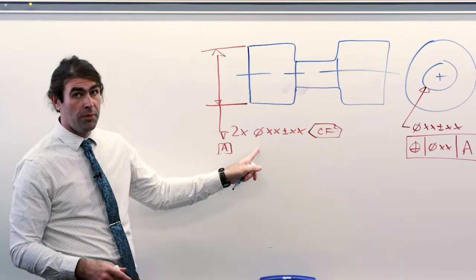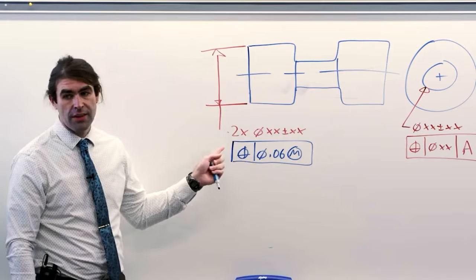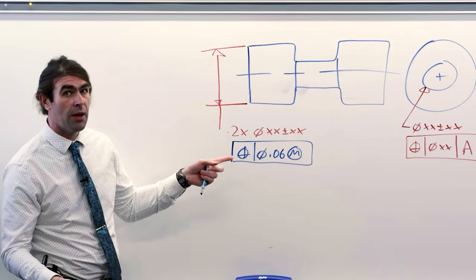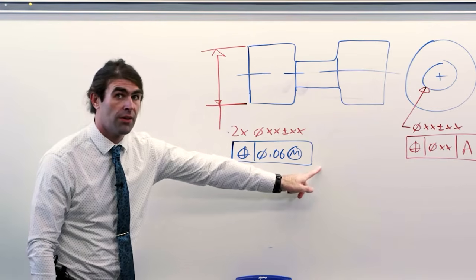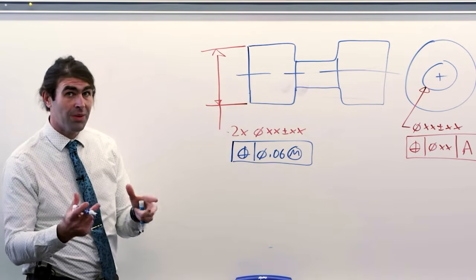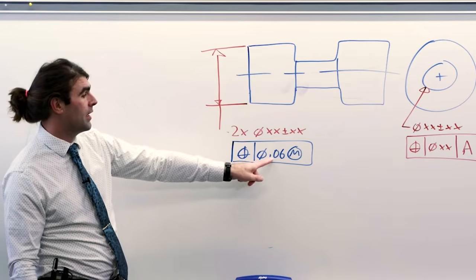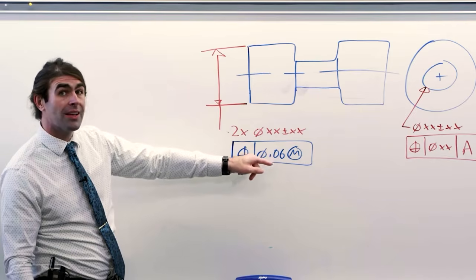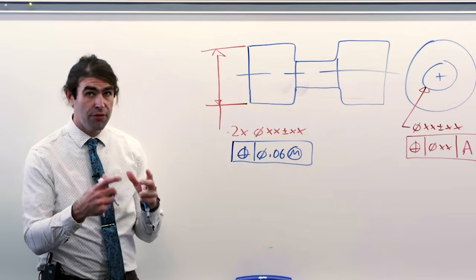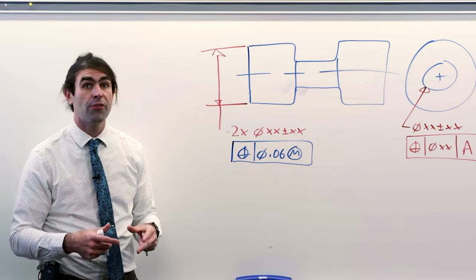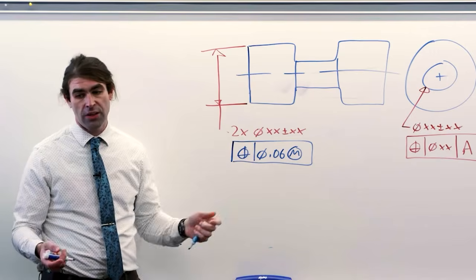Well, this is going to limit you just a little bit compared to if you use this concept called position tolerance without datum references. Now we're relating these two diameters with a position tolerance with no datum reference. So we're essentially saying they're related, but now we can get a material condition involved. So now we could say it's got to be within whatever at MMC, but you're going to get bonus tolerance if these two cylinders come in small, and it's still going to fit through whatever you want it to fit through. So if you can accept these two cylinders becoming smaller, this might be the way to go.